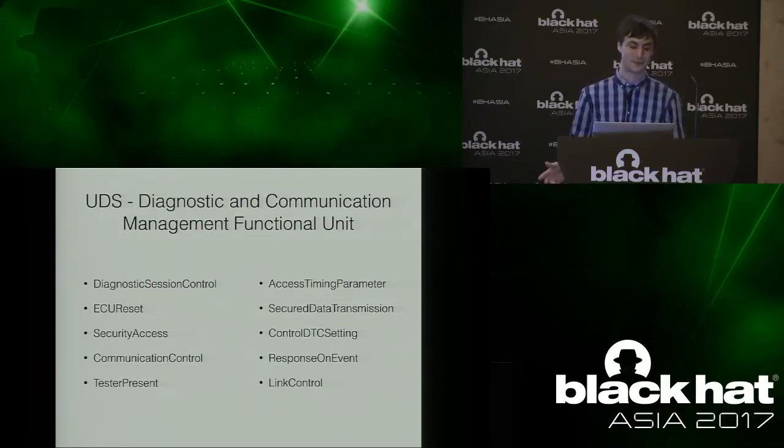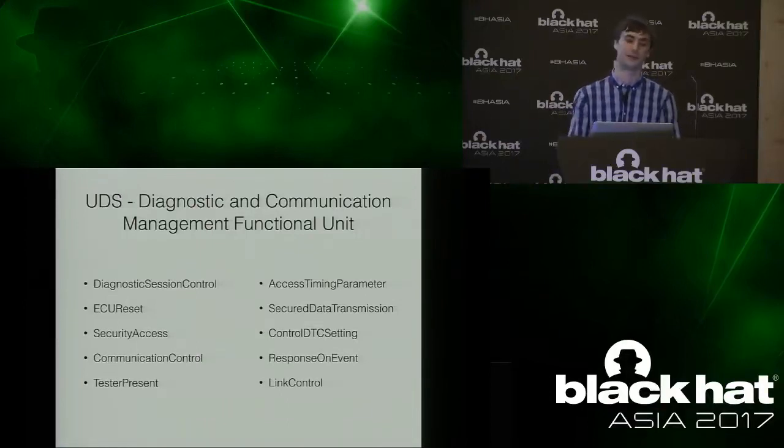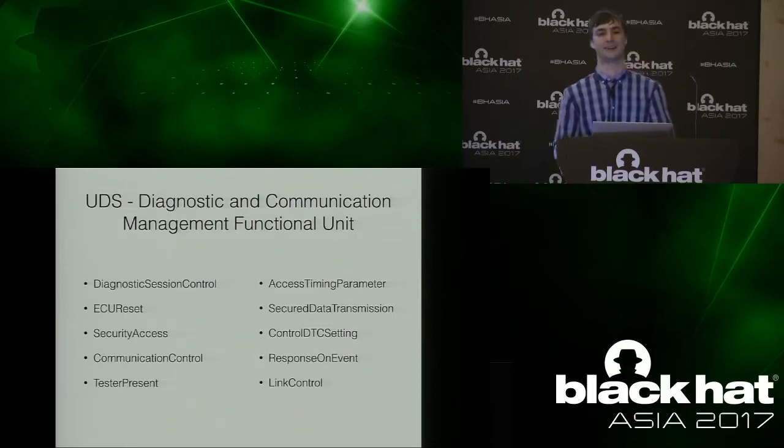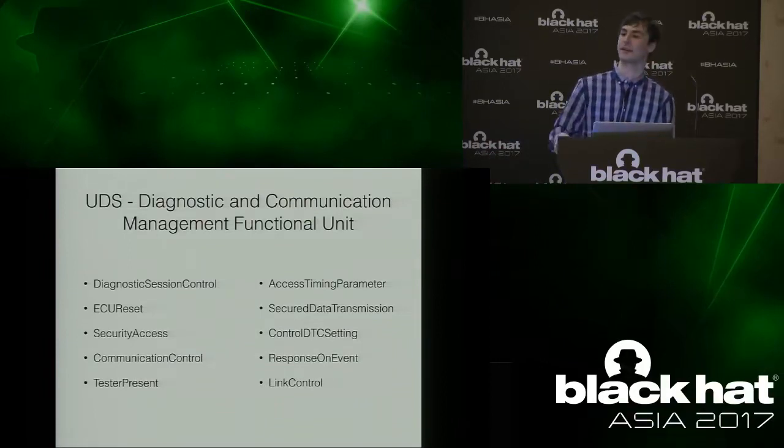Now, this is potentially useful to an attacker because if you can make that operational data stop from one controller, you can inject your own frames. You can do this anyway, like in the demo we showed before, by spamming frames onto the bus. But sometimes you'll end up with issues where you won't quite overrun the buffer correctly or whatever, and you'll get blips where it will receive a valid frame and it will reset a state. Doing this, you're actually able to make a controller completely stop talking. It also gets around problems like a sequential counter in the CAN frame where you can't easily inject. So communication control is kind of interesting for that.